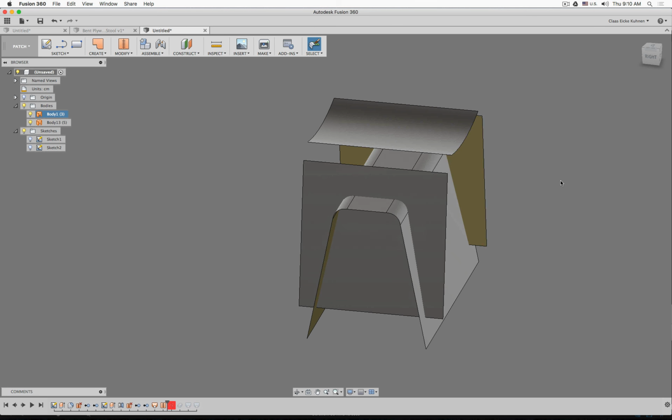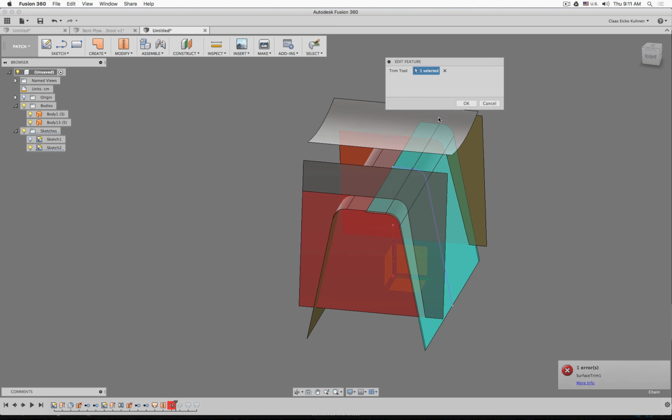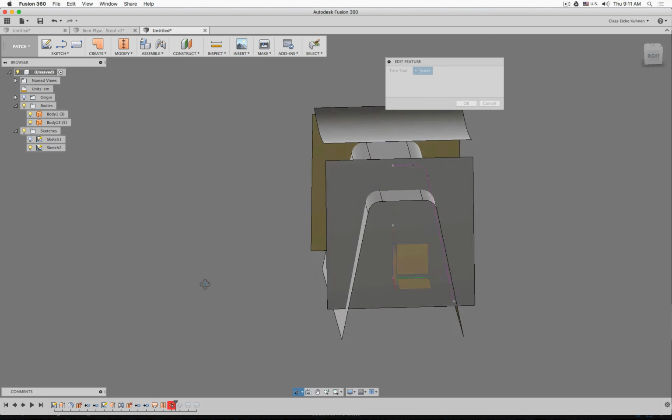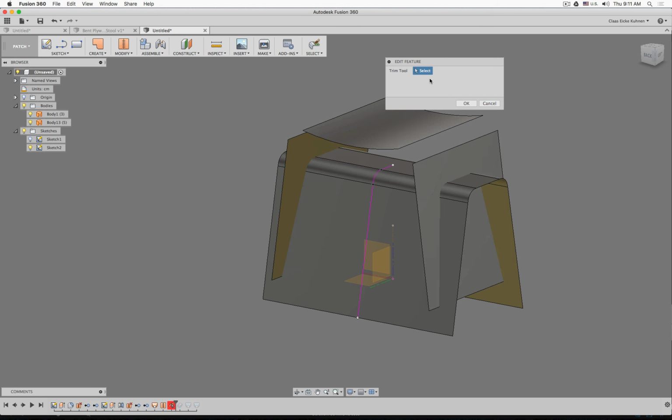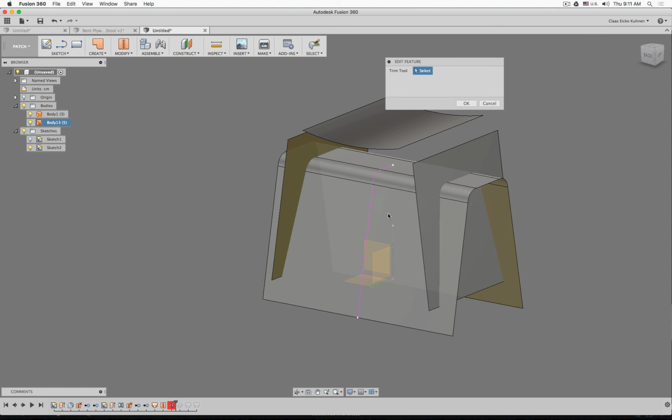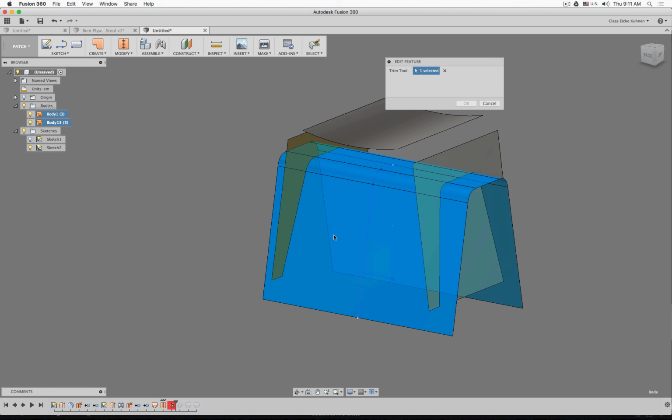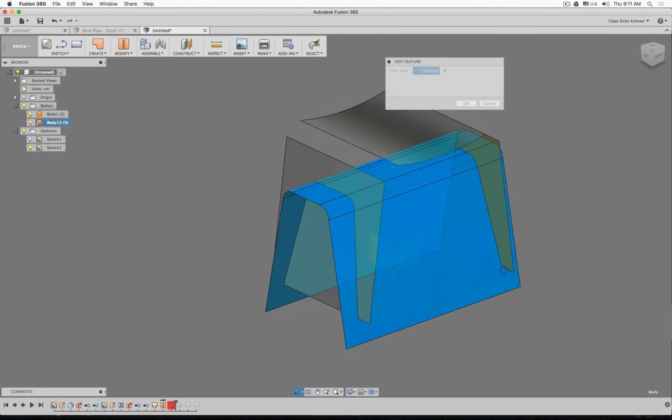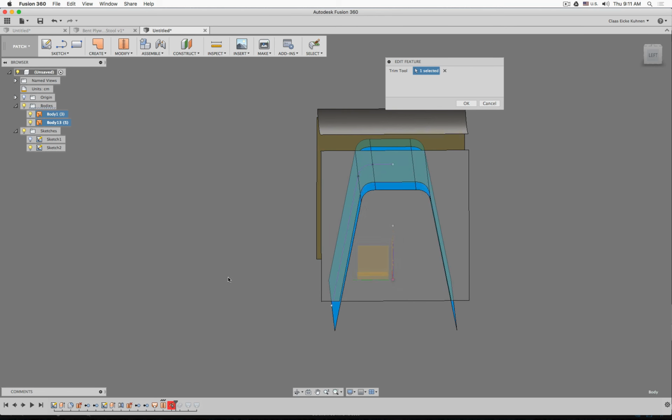Again, what I tried to do was simplify my geometry or reduce the amount to help the software to prevent any interesting misunderstandings. So the trim command is still saying WTH. So right click, edit feature, and it tells you, yeah, nothing works. That's okay, because we have to delete the tool selection. Instead of the sketch, now we select the surface object. And because we stitched it together, it understands this is one big object.